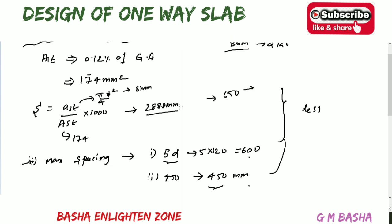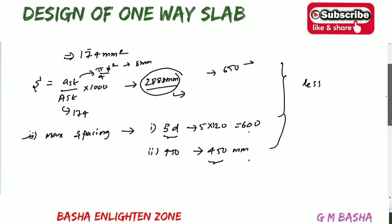But here our obtained value is 288, which is lesser than these two, so we can provide this 288 spacing. Again you can round that value to a nearby value, 280. So I provide 8 mm dia bars at 280 mm center to center. So this is the procedure for finding the distribution reinforcement.